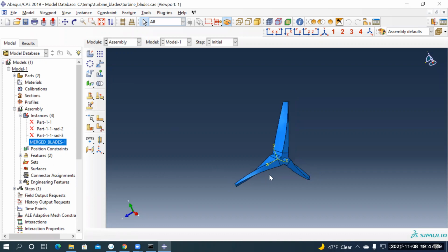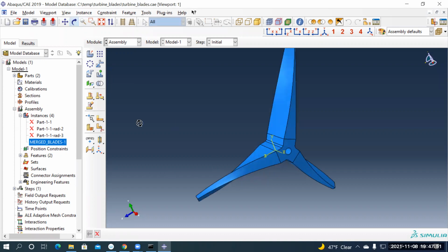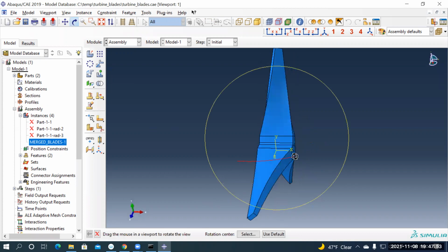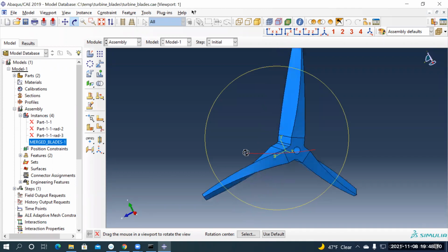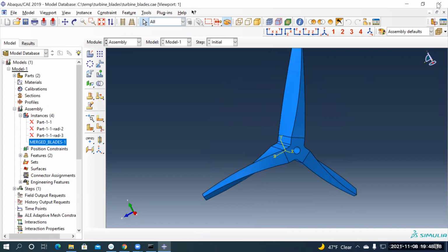All right. So we'll take one of these blades and use the extended finite element method. The crack has to generate wherever there is more stress concentration. That's the location where the crack will start. But this is a complicated problem. We'll start off with tensile testing, crack propagation in tensile testing, and then we'll go to the wind turbine blade fracture mechanics. Is that okay?